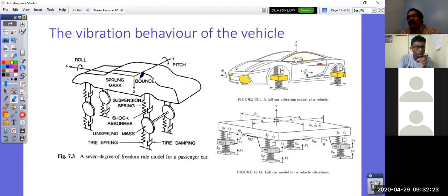You do not really require a laboratory 4-post rig where you put the vehicle and put the dummies inside with instruments, which are representing the humans and so on. So this is a complementary approach, analytically, to get the right parameters of the vehicle, which are essentially natural frequencies, amplitude ratios, and the damping or the phase information between the vibrating lumped masses.